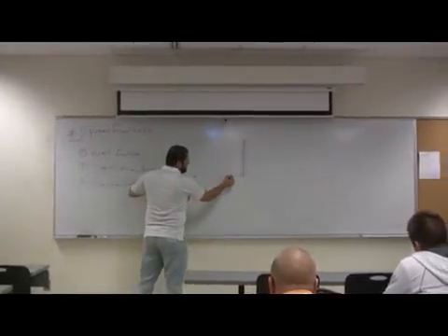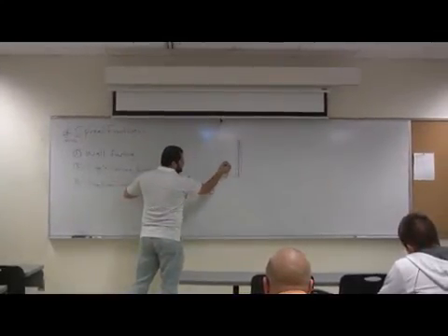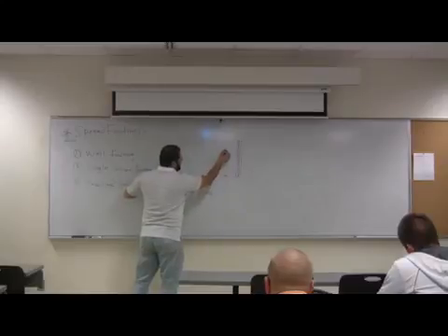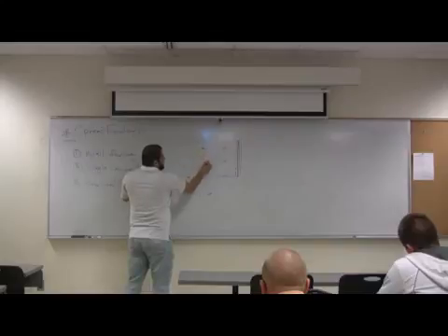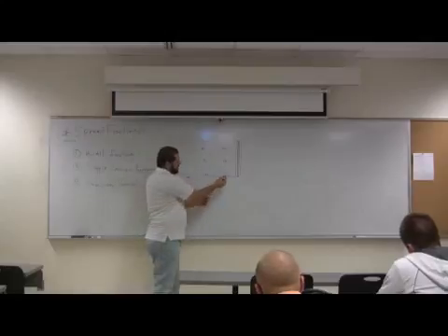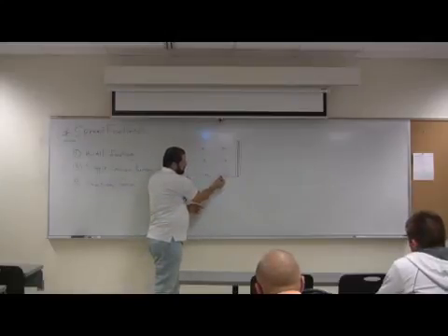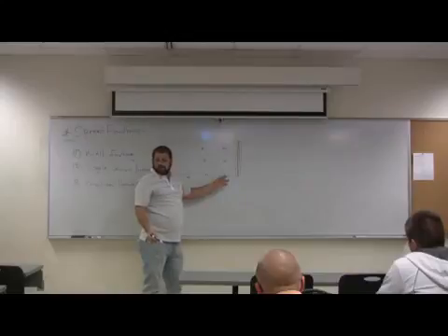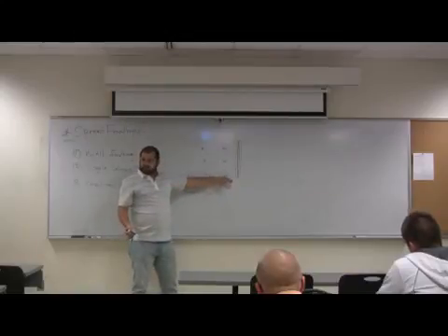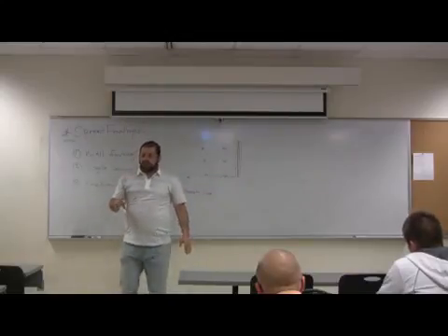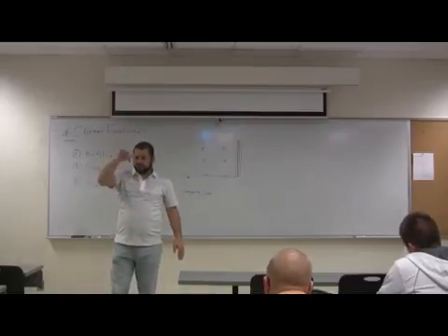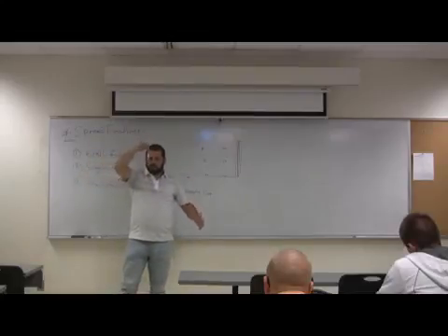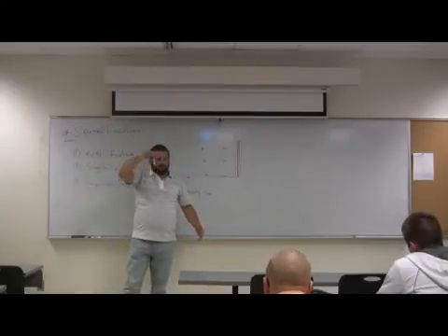So you may have an interior column somewhere in here, another one, the column lines like what you have in the project. For this column, if you want to create a single column footing, you may not be able to do that because this is not your line. We always look for the column to be concentric in the middle of the footing, so that it's considered pure axial loading.